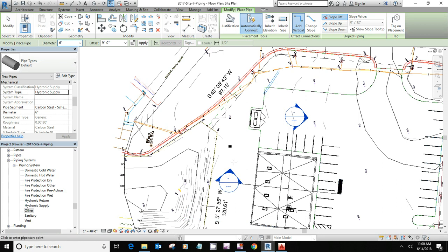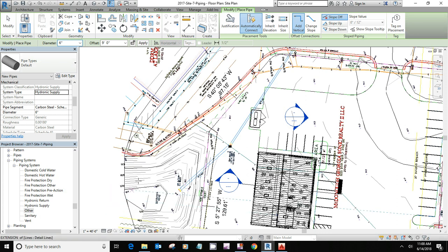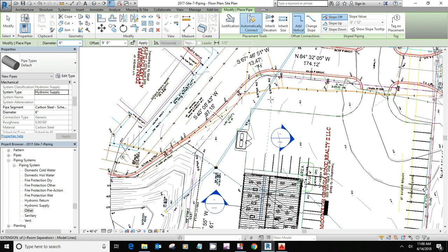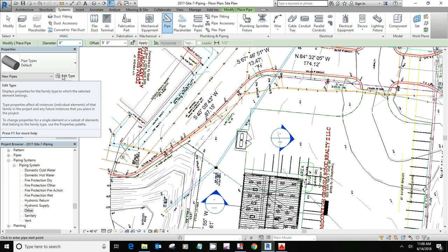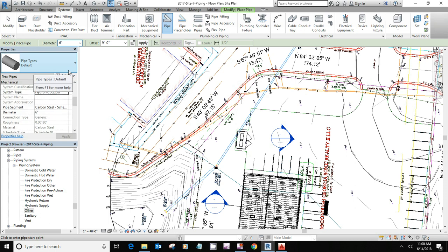So we go to Revit. I'm on my site plan layer, and I'm going to switch over to wireframe. That way I can see through my topo surface and I can see the location of these pipes, okay? Now, what we'll do is we'll go to systems and we're going to go pipe. We don't have to create a new type. We can go with this.